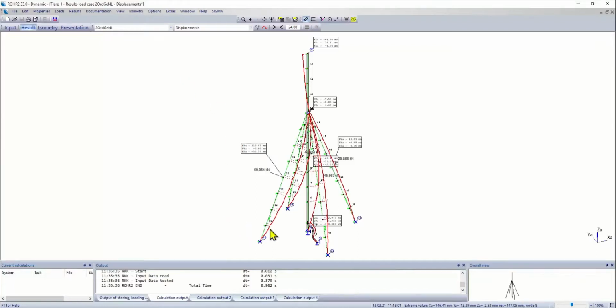So this is not necessarily the way I would analyze this situation. I will probably replace these ropes here just by equivalent springs, and I would still get reasonable results here. And I would not try to figure out the exact bending curve here in the ropes in this case, but I'm interested in the piping system itself.